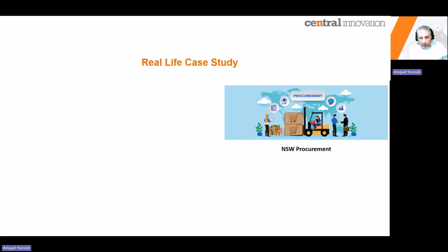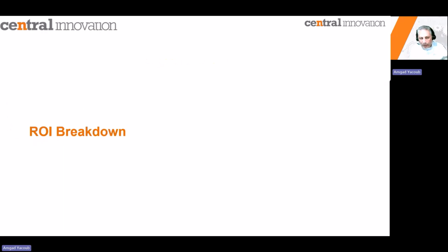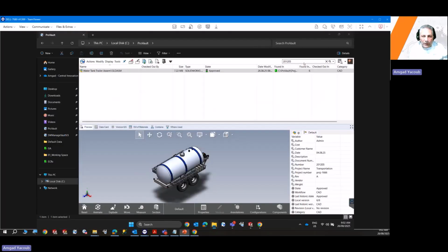Right, so without any further ado, we are gonna do the engineering change request process and integration with MYOB, but from the other end, from design to production, rather than from production to design. So straight away, we are gonna jump to our case study here. We are inside SolidWorks PDM. We have our container here, and because we had some engineering modification to this container, we decided to reduce the number of tank stripes from 3 to 2.